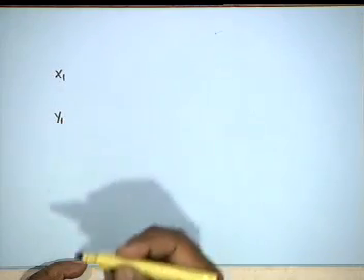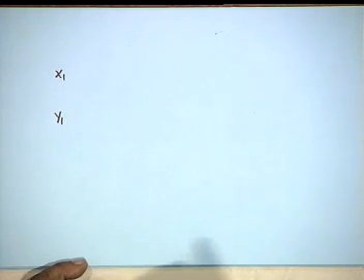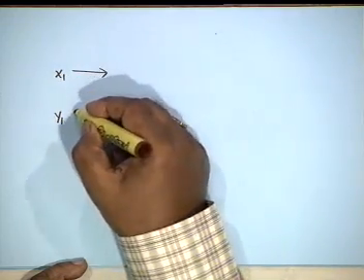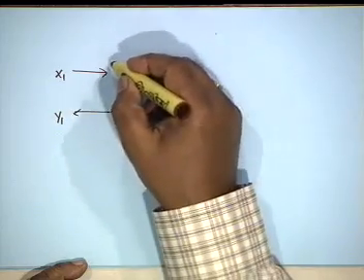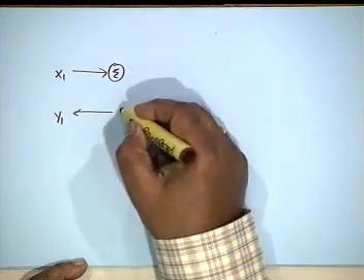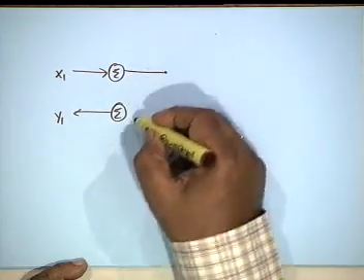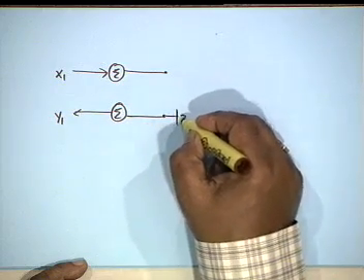Let us see. The structure, now unfortunately I have to draw the total structure. Please draw with me. I can't do it with boxes because I am going to analyze. The total structure that we are envisaging, well, first we draw the all pass structure, then we shall see the taps. Okay. X1, Y1, we have 2 summers and a Z inverse.